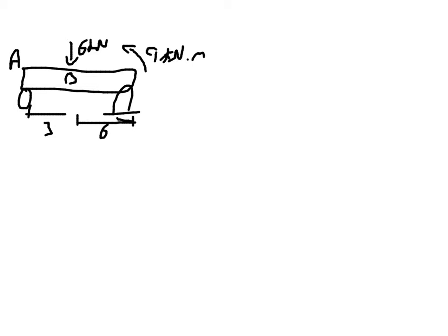So if we ignore the forces at the ends for now, you can have a support reaction at each end, and let's say a Y reaction and an X reaction at this point here. This is point D. You could have an X reaction because that's a pin joint, but you can't at point A because it's a rolling joint.